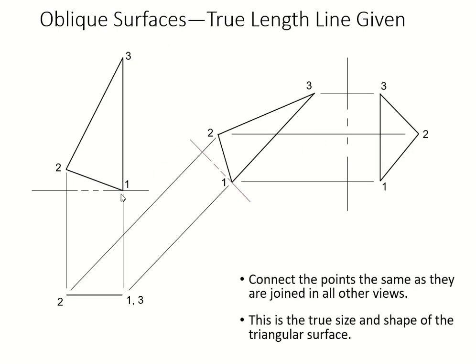Now we're going to get rid of all of our drawing stuff. So we have nice and neat little projections right here, and that's our top view. We keep the true size and shape, of course. Alright, so that's the end of the given true length line problem. We get the third view, the edge view, projected from your true length, and your true length came from your line parallel to the first fold line. Alright, that's it for this section.